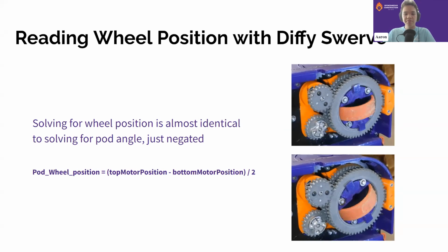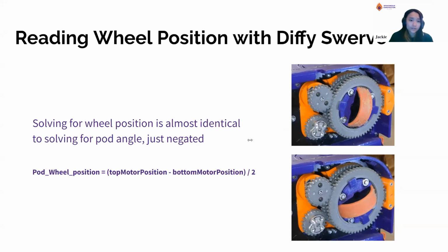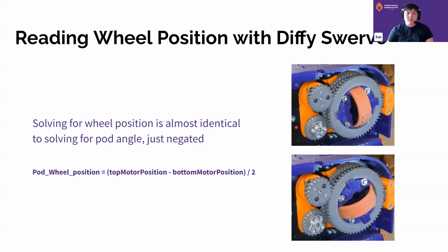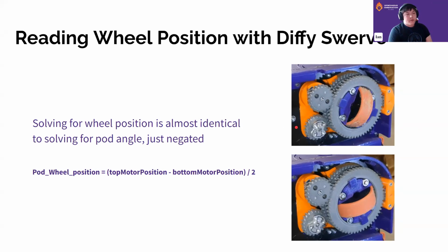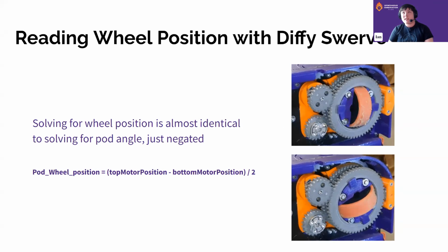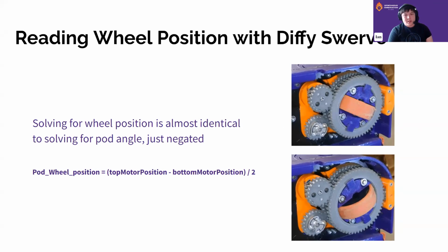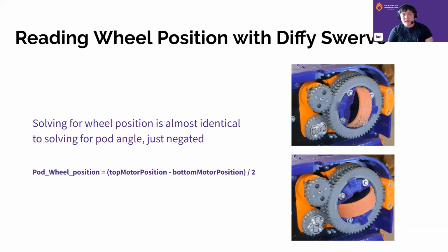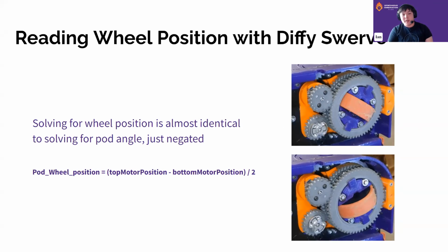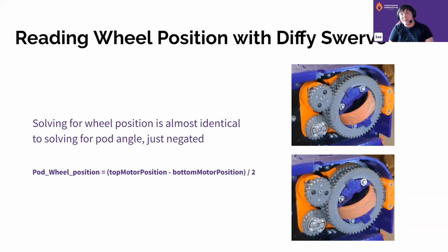So yeah. We also have a question: what gear ratio did we use for our motors? And we can also talk about the gear ratio we used for the gears. For the motors for our swerve drive, we use goBILDA 312 RPM Yellow Jackets, and those connect to a 20-tooth gear, and the gear ratio to the rotation of the pod is 20 to 52. But for actually rotating the wheel in the middle, it is 21 to 10. Sorry, it would be 21 to 52 and then 21 to 10.